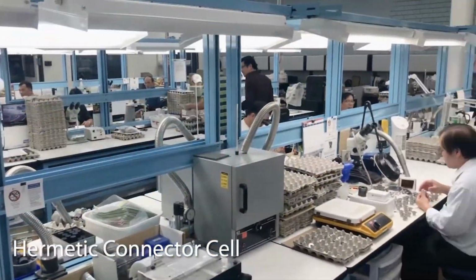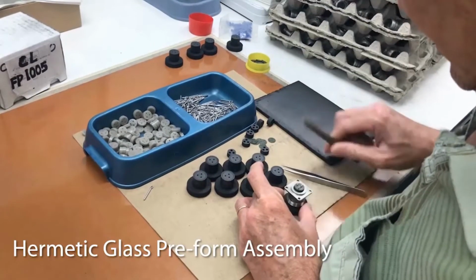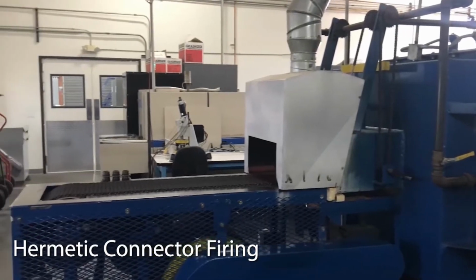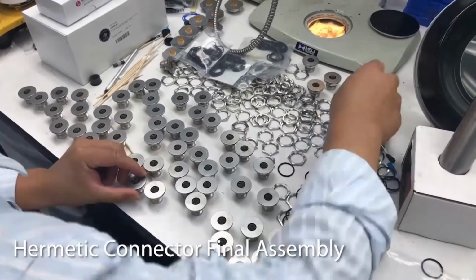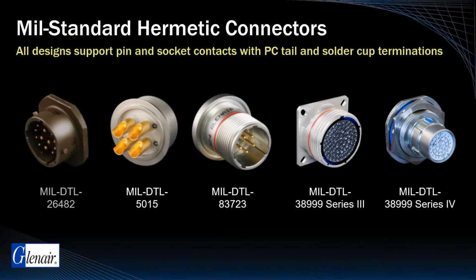The process of building a hermetically sealed connector may be applied to virtually any connector series, given suitable shell materials and wire terminations. Glenair offers Hermetic class connectors in every military standard connector series we manufacture, from legacy power and signal cylindricals such as 26482, 5015, and MIL-DTL 83723, to higher density aerospace interconnects such as the D38999 Series 3 and 4.